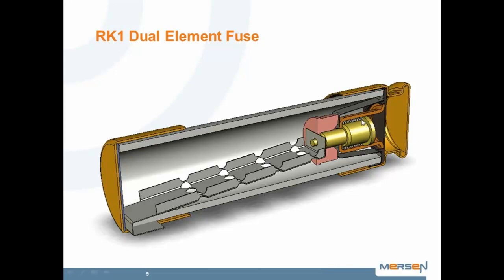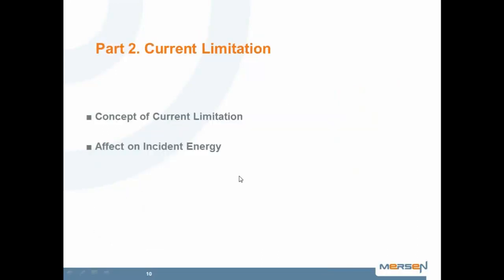If you are having an electromagnetic assembly like this, or even a circuit breaker, it has inertia and springs and time that's going to delay the actual opening of the circuit. With this, it's only dependent upon the current. If you have more current, it will operate faster, because if it melts the silica sand, it will turn to glass, and it's very high resistance, and it will open the circuit.